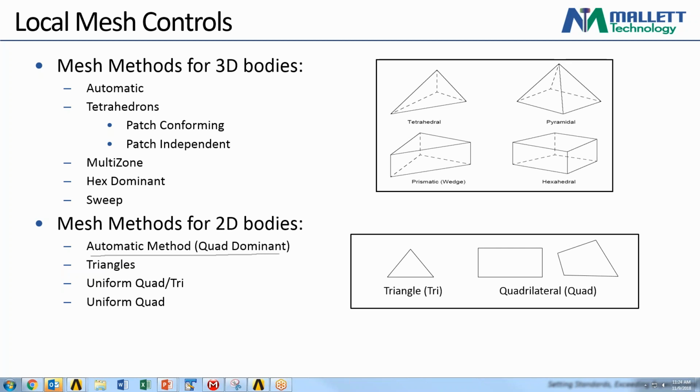So the short answer is it just depends, right? Especially for contact results, it's much more a factor of element refinement as well as the method the contact uses to detect the other contact. So the default method is Gauss points, which potentially can concentrate contact pressures on nodes or they're projected to nodes.